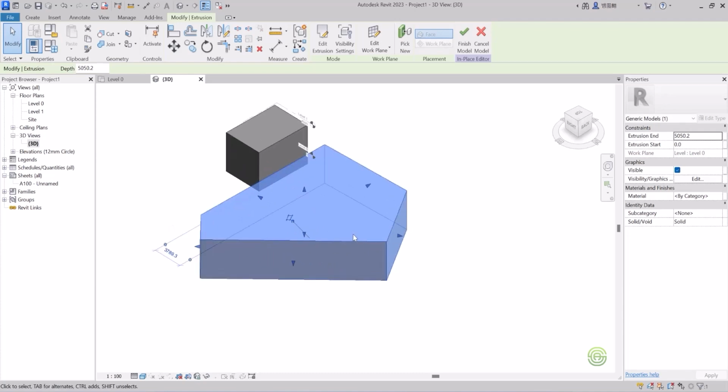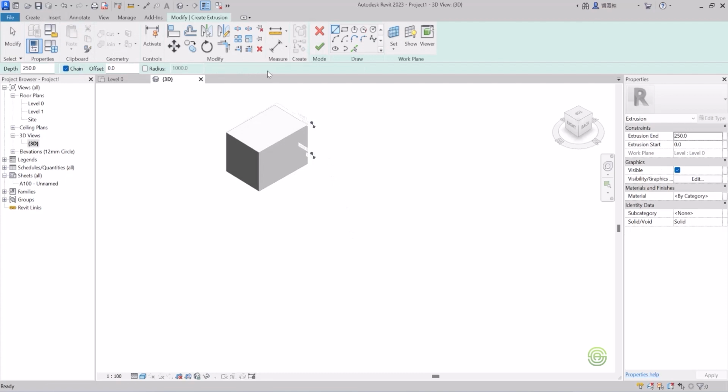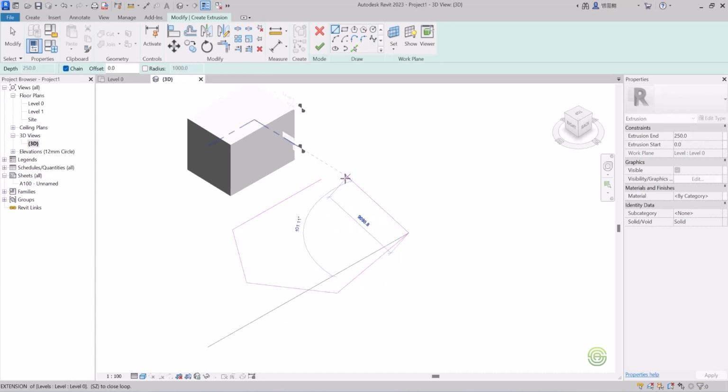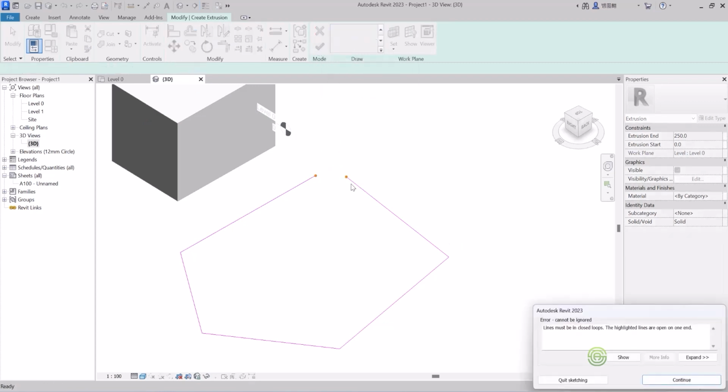So I'll show this again. See, if I delete this, now if I go to create and select extrusion using a line tool, just select the line tool and then click here, move your mouse cursor and click and move randomly like this. Now see, if I don't bring my cursor to the endpoint but just leave my click here, and now if I give a green tick, I have an open side here, I didn't close this line. So it is not proper. Now if I give a green tick, I cannot extrude this because I have not closed it. So it will show like this.